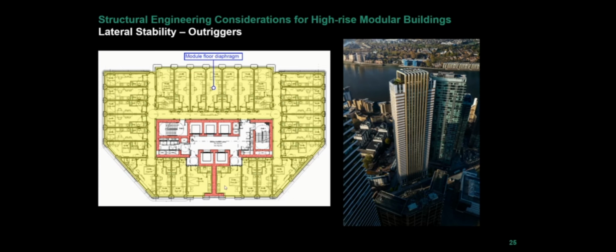So the core walls were on the left-hand side and right-hand side of those apartments to give us the amount of stiffness we needed for the core to work for deflection and accelerations. But due to deliveries, and there were a few issues with the rate of rise, it wasn't actually possible to slip form a core that big with the travel restrictions and lorry restrictions in Canary Wharf. So our client requested that it wasn't feasible to build this job unless that core was reduced.